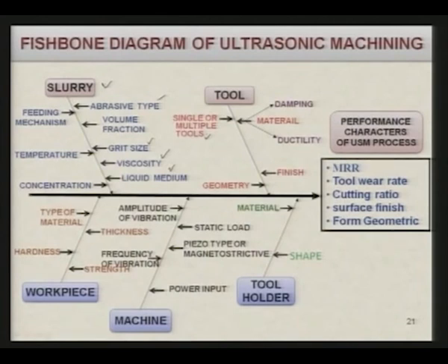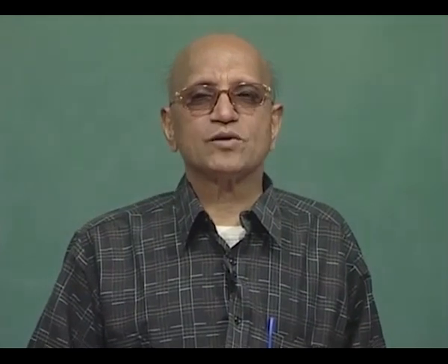Another very important parameter is the finishing of the tool, because, as I mentioned some time back, if scratches are there or micro cracks are left, it will quickly fail because of the ultrasonic vibration and the load acting over it. Also, if the finish is not good, this will be reflected to some extent on the finish of the machined component, and definitely the geometry of the tool will affect the geometry of the machined cavity that you are going to get on the workpiece.